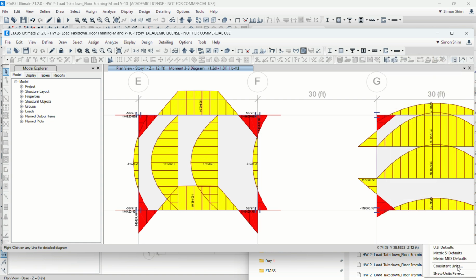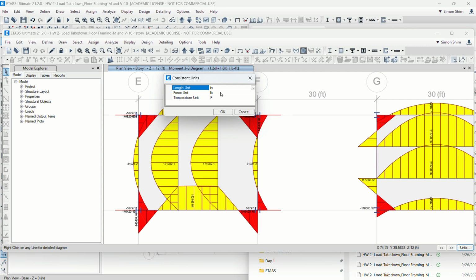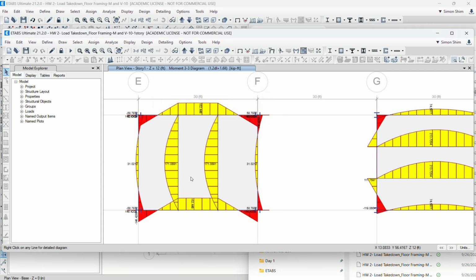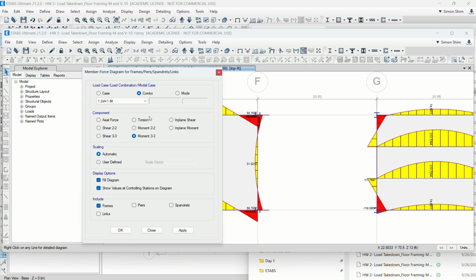So keep. I'm going to change to keep. You don't want to change the feet. 171 versus 154. Now there's some power discrepancy that might be happening. Oh, beam weight. We didn't include a beam weight, right? Then let's check only live load, because we didn't consider it. So live load moment. Let's check live load only, pure 1000, right?